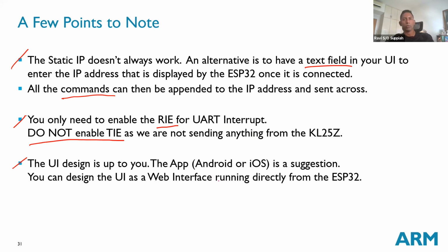Because your ESP32 is actually running a web server, you can run your user interface directly from the ESP32. Just let it boot up and show the user interface at the IP address it connects to. So it's up to you to decide how you want the user interface to be designed. App, web interface, anything is up to you, because now you are just dealing with IP addresses.